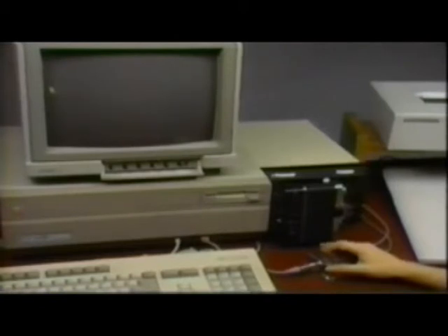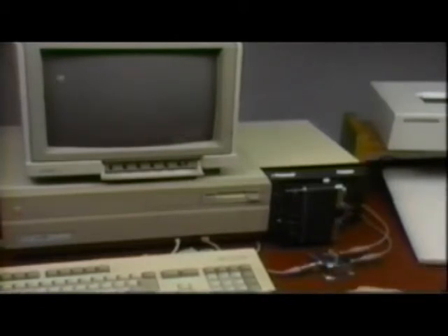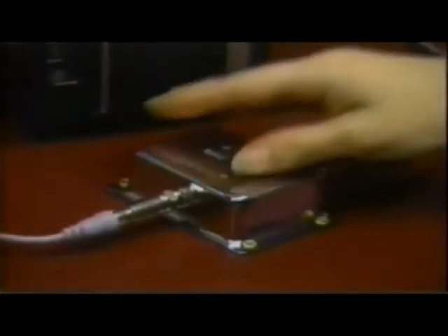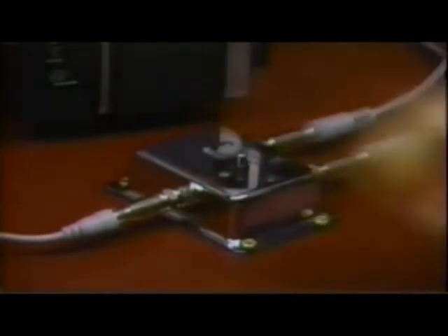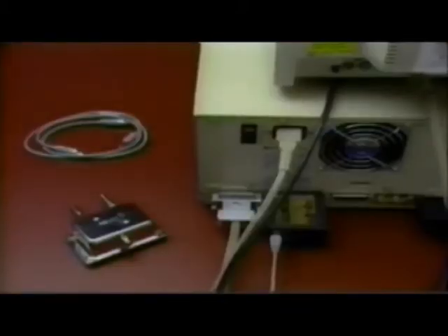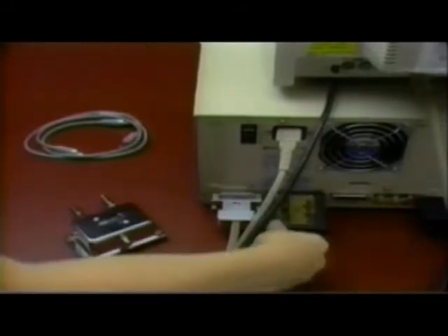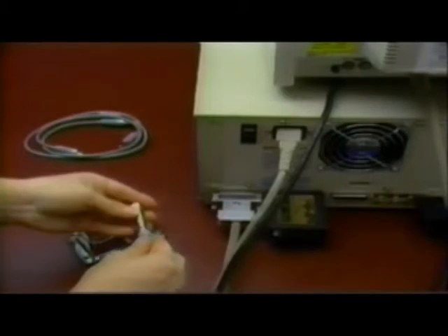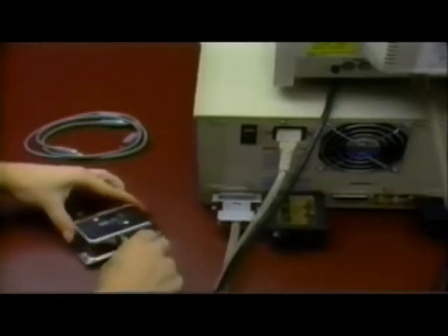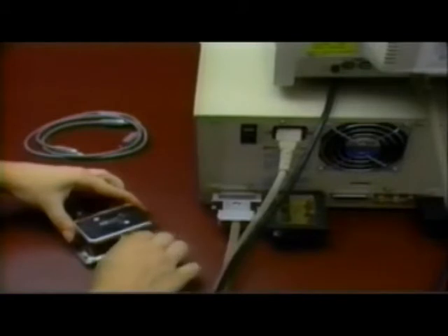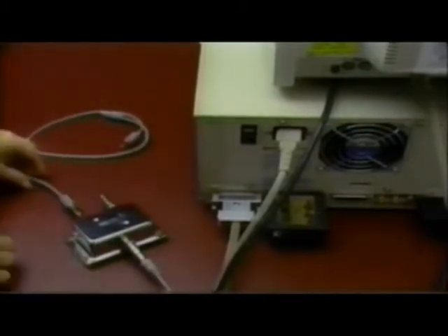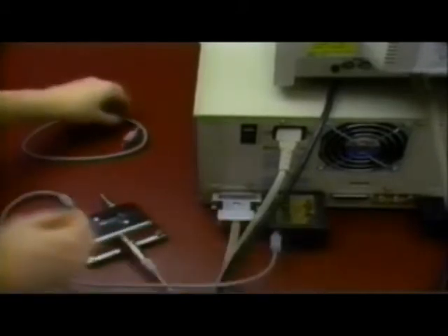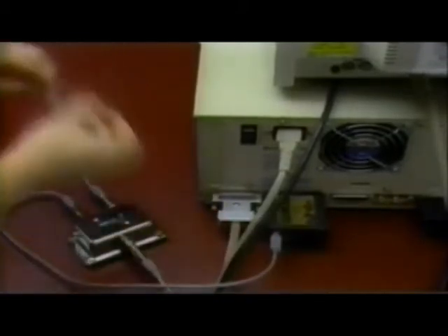Instead of unplugging and redirecting the cable, a composite video switch can be installed. The switch will direct the camera's output to either the DigiView interface or the monitor. To install a video switch, the camera cable must be attached to the input slot of the switcher. A screw-in coaxial or plug-in BNC adapter may be required, depending on the type of switch box and cable used. Two more cables are needed to connect the DigiView interface and the monitor to the output slots of the switcher.